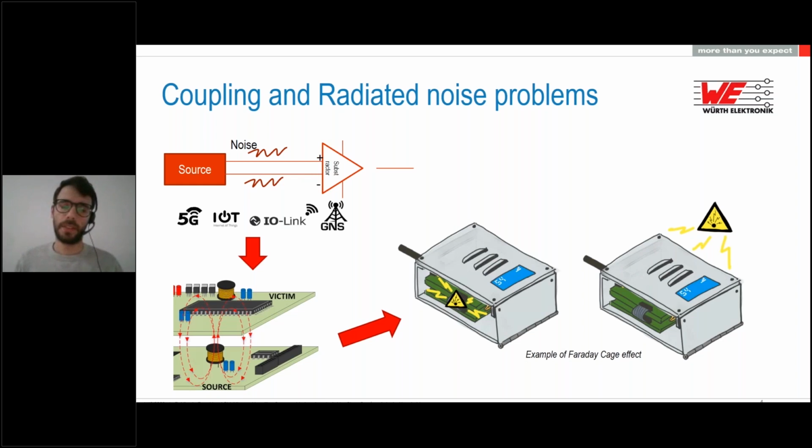In the one on the left, we are using the Faraday cage to contain the noise that is generated by our design, so it is not affecting external devices. By normative, we have to pass a lot of certificates about EMC and tests, where in the lab it is tested what the amount of radiation is that our device is radiating to the environment.